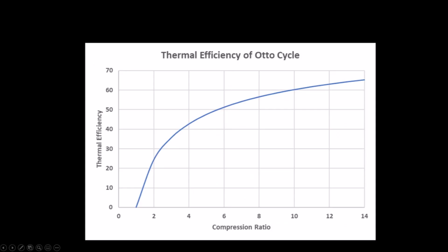Here is a chart that is in all of our mechanical engineering and thermodynamics books. The Otto cycle is a thermodynamic representation of the spark-ignited gasoline engine, and the chart tells us the maximum efficiency of the cycle is a function of the compression ratio. Those engineers that like to pick nits will say it's not really the compression ratio, but the expansion ratio of the engine. In the Otto cycle, they are the same, which is not true of real engines.